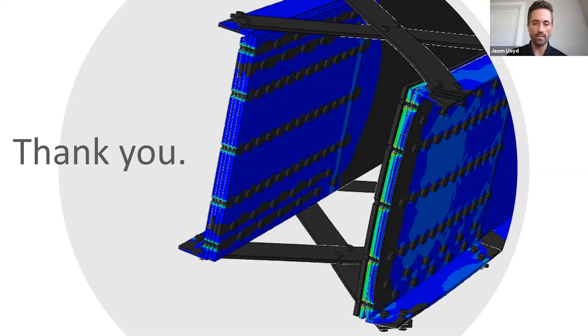And like I said, it's cooled to a point where the steel is as brittle as possible. And then we would hope that it would fracture, because the test itself really needed to see a brittle fracture event, that sudden and violent release of energy.